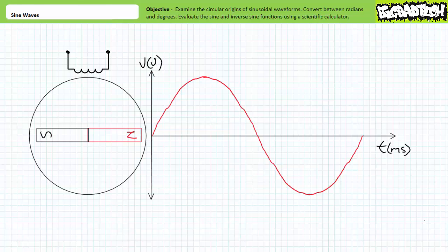When a north pole is close to the stator, let's assume it generates maximum positive voltage. And when a south pole is close to the stator winding, let's assume it generates maximum negative voltage. As the rotating magnetic poles approach or recede from the stator, the circular rotation and resultant induced voltage waveform can be modeled as a sine wave. Given the magnet starts operation at 0 degrees with both the north and south pole equidistant, no voltage is generated.